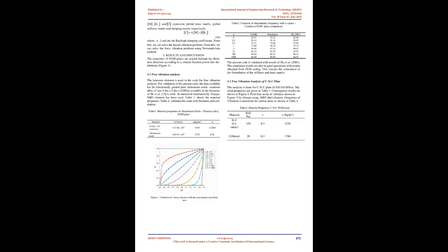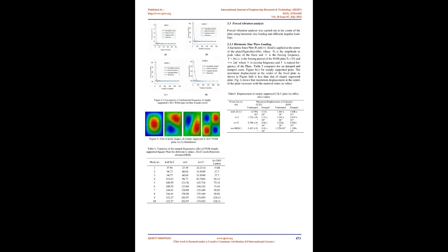A computer program is developed using Matlab to implement the finite element formulation and include all the necessary parameters to investigate the vibration behavior of the FGM plate. In the present code, a selective integration scheme is incorporated for the generation of the element stiffness matrix. The 3x3 Gauss quadrature rule is adopted to get the bending terms, and the 2x2 Gauss rule is used for the shear terms to avoid possible shear locking. The mass matrix is evaluated by using the 3x3 Gauss rule (12).